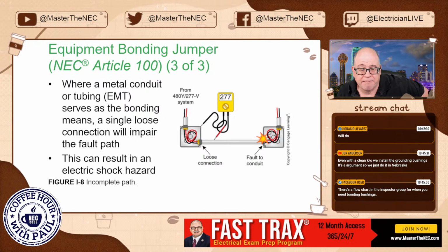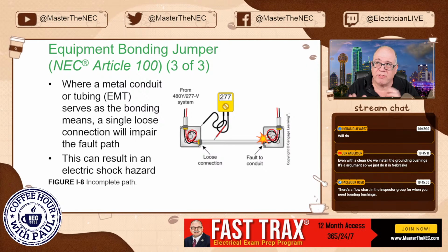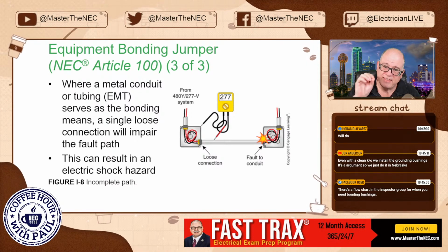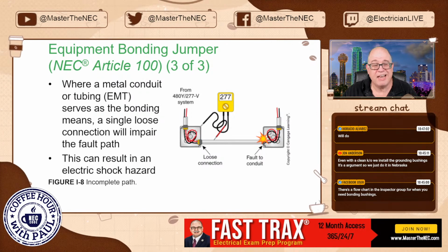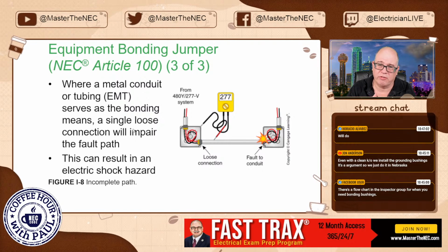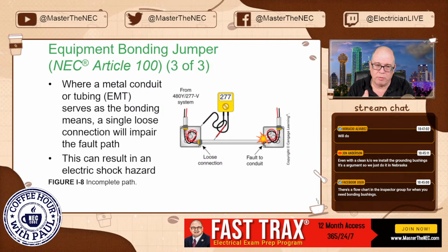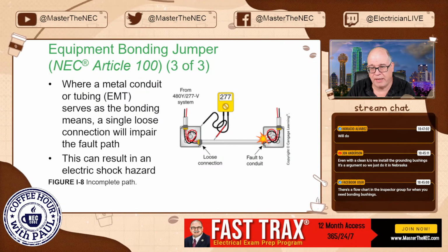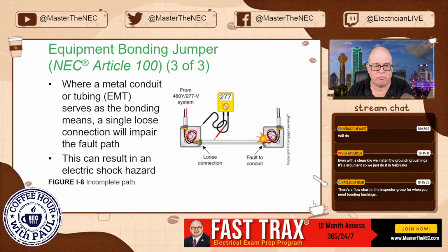And here's the funny thing. Well, I don't know, it's not so funny. I mean, I shouldn't say funny. This can sit there for quite a while and not clear an overcurrent device. So, loose connections, folks. It's so important when the code tells you to make things up wrench tight that you literally do it, and that you do the tightening, and that you do all your set screws properly.